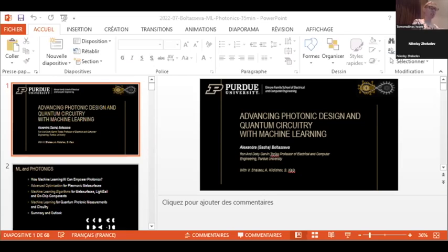And what we usually do is to start with a concept, and this can be a waveguide or a structure that you would like to implement, or it can be some structure where you want to study fundamental optical effects, and then you usually do numerical design, right? To do some numerical simulations, you see what dimensions, what kind of implementation is really feasible. You check which materials are available and do the fabrication, integration, and finally the demonstration as well.